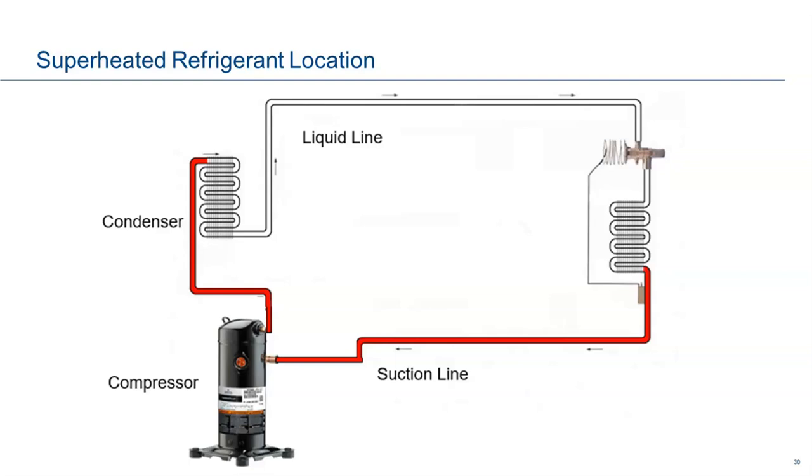What's the significance of 300 degrees? The significance of the 300 degrees is oil starts to break down. So this is a nice way, because we can't stick a temperature probe inside the compressor, can we? This is a nice way, with just taking temperature readings, to tell what's going on inside your compressor, okay? Again, don't go any further than 6 inches. Take your temperature reading. Always make sure.